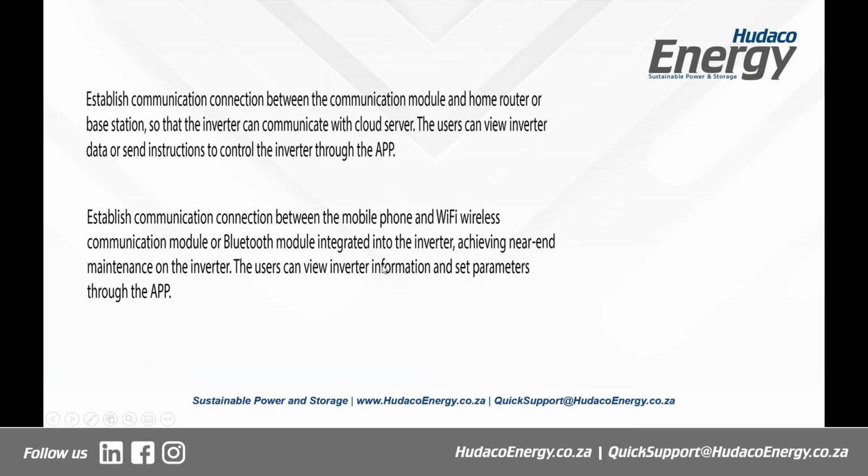Okay, if you use the Bluetooth or Wi-Fi connection, which is the near end one, you can only view inverter information and set parameters. You can't send instructions. Okay, so there's a bit of a difference as to what you can achieve depending on what kind of connection you have. We'll see the difference in a few moments to come.